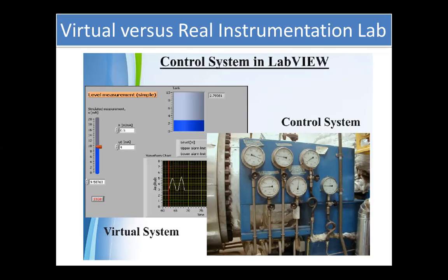Dr. Ashwani is asking, is it possible to do real-time measurement using LabVIEW? Yes. Through your TeamViewer, you can do it. The only thing is that you have to have someone to put the device under the DUT. Ashwani can understand what is DUT. The DUT in your test bench or your probe station. And then if you can configure the probes, if you are using cascade probes, you can download the probes and then you can put it on top of your DUT. After that, if your network analyzer is on, if your power supply is on, everything is on, then you can access it through the TeamViewer, your LabVIEW program sitting at your home. Because TeamViewer is nothing but you are accessing the system which is there in the lab.